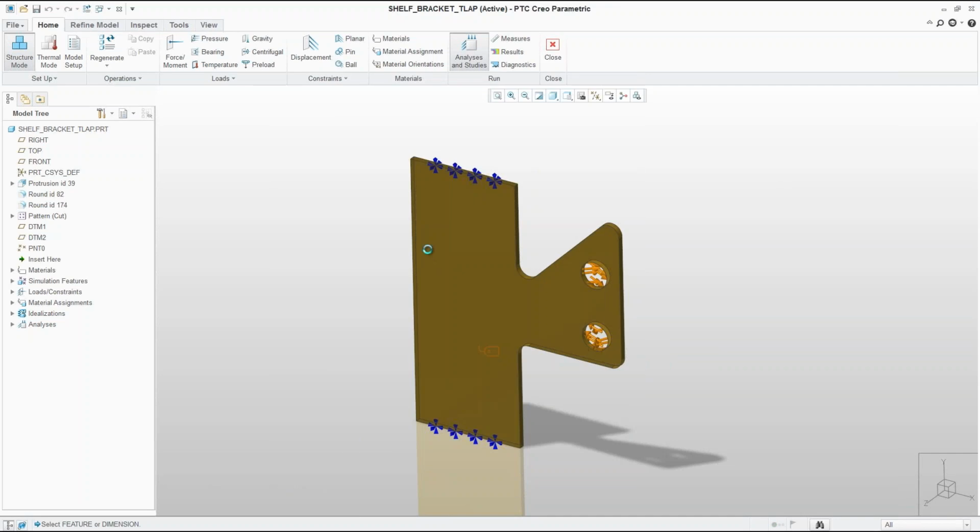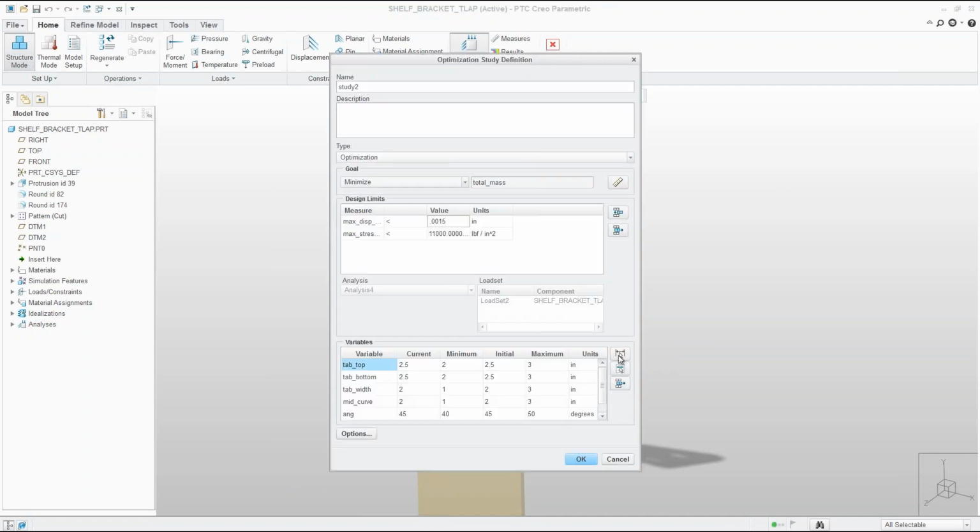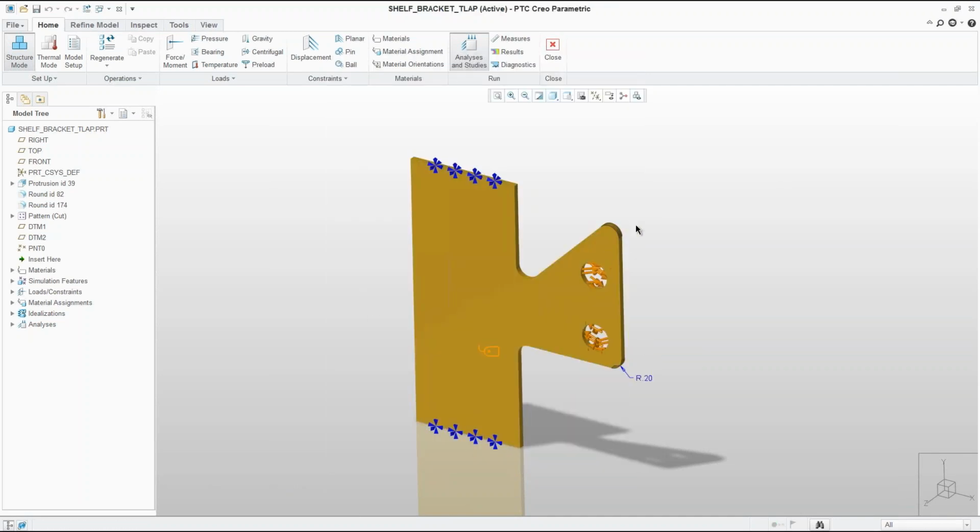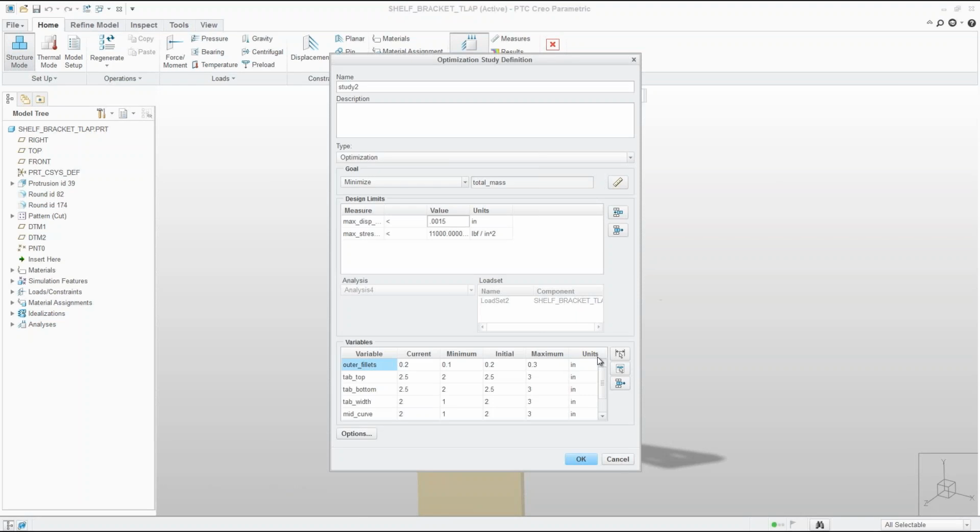So just going through, picking some different measurements that I think we can improve upon, and telling the system, hey, change everything for me, run through. I just want this basic shape in mind, but run through and give me a completely different optimized shape. And I'm going to say specifically what range I'm concerned with. This thing can't be too tall, it can't be too wide, but we have a lot of flexibility in between maybe. So I select what the minimums and maximums are going to be, and then have the system run that analysis for me and spit me out a completely optimized shape.